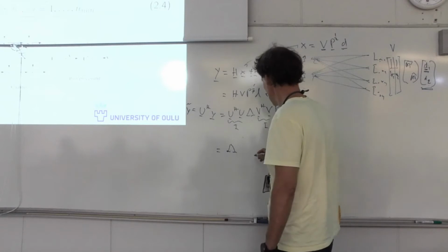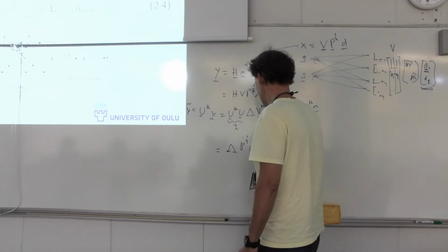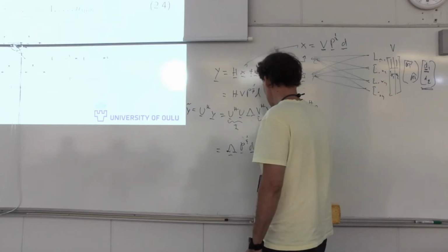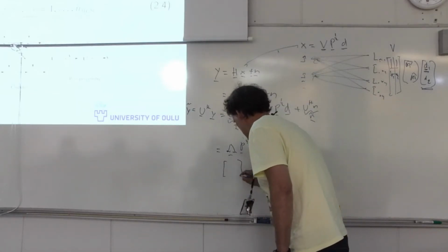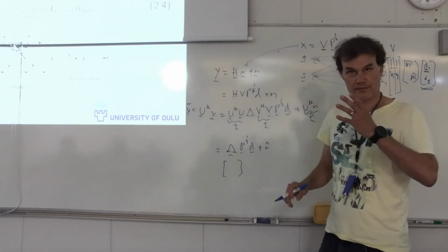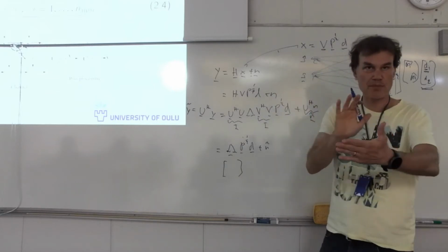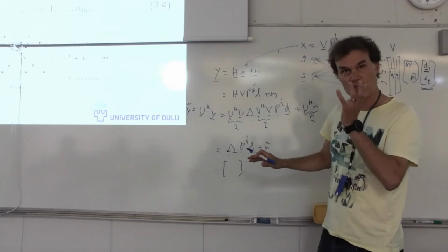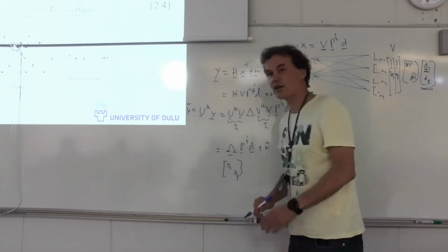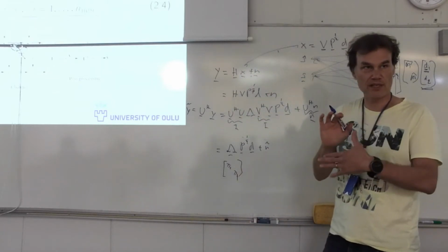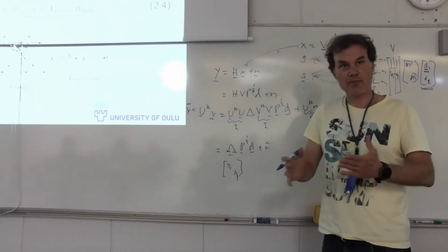Lambda square root of P D plus n tilde. You can see that this Lambda is now the equivalent channel matrix after pre-processing by V and post-processing by U. It diagonalizes the channel matrix. We have a diagonal channel, meaning that there's no interference between D1 and D2, right? So it's easy. Now we have a parallel channel, so we can process them separately.